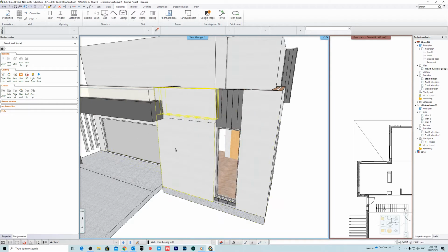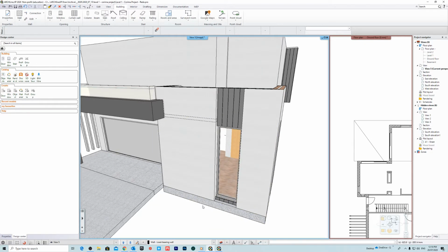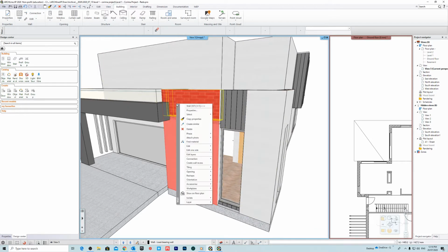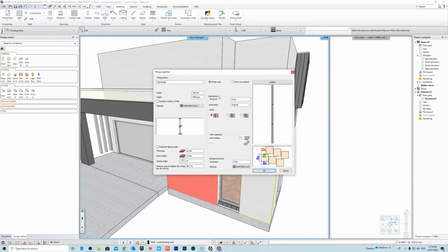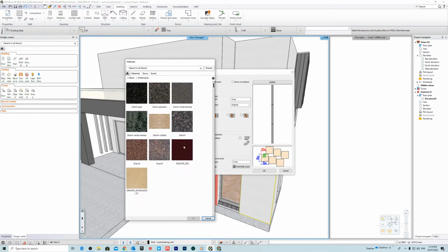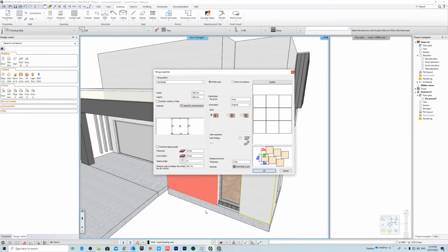Okay, so I'm just quickly going to check my tiling sizings. Okay, so the sizings of this tiling, so we're just going to place the tiling first. So we'll go right click, tiling on wall side on this wall only. Okay, then we need to make some changes, right? So firstly, for the material, we'll just go and find a nice stone finish. So probably this one over here.